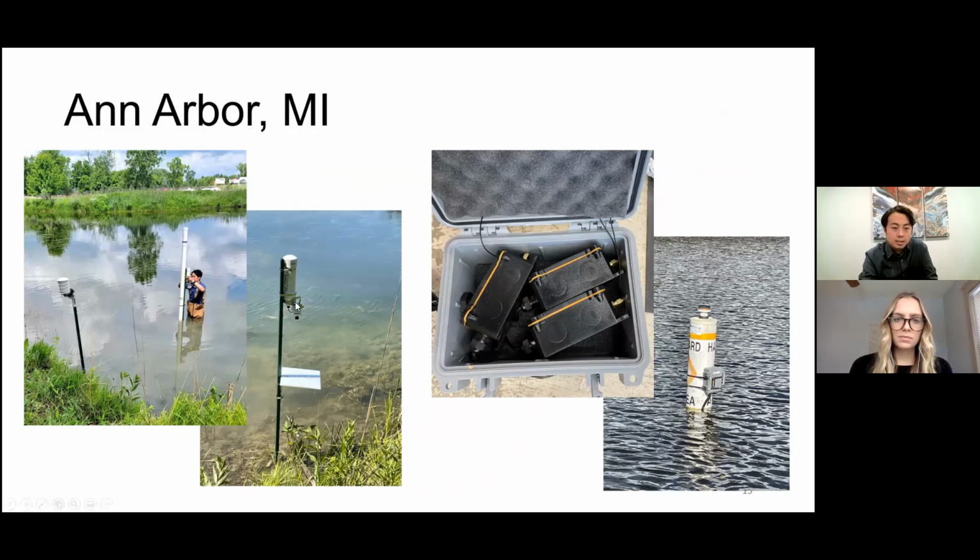This water level sensor, which is mounted nearby, we have put a fixed plate so that this sensor is measuring at a fixed distance, compared to the sensor in the pond measuring the water level that's always changing. And from our experience, the water level sensor doesn't change much. There's no substantial drift that we are seeing for the water level sensor.